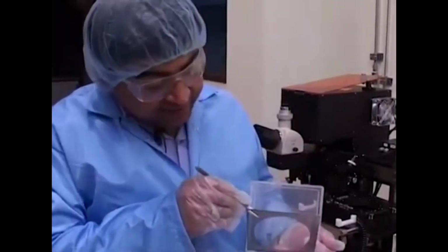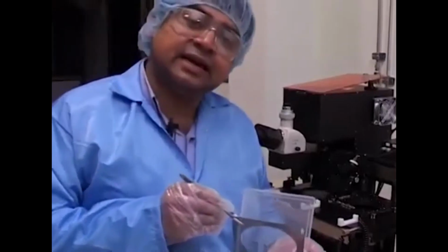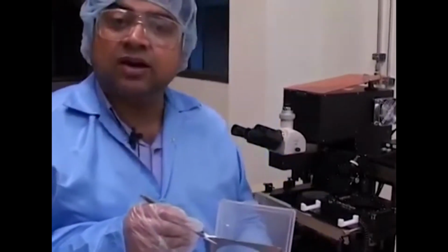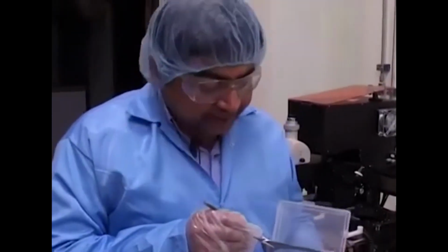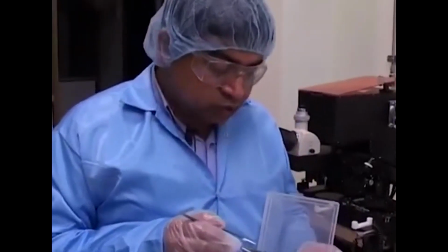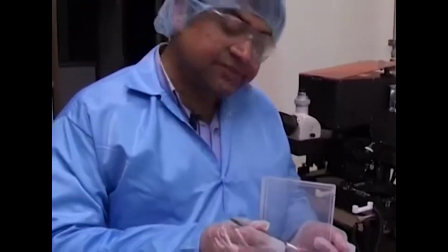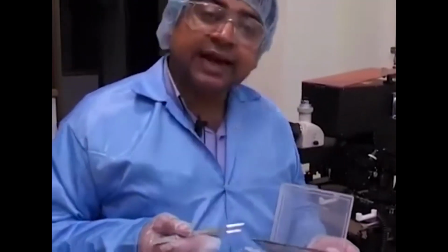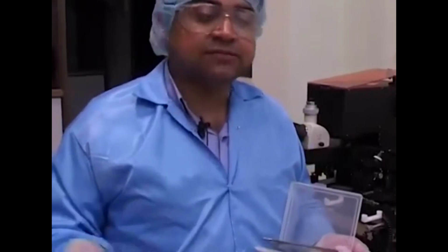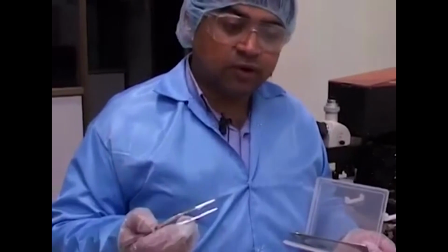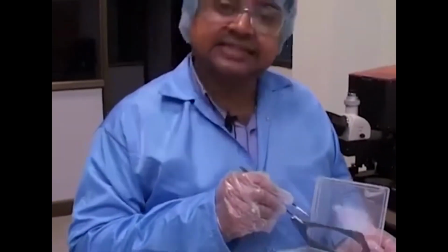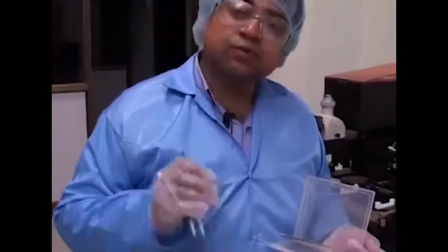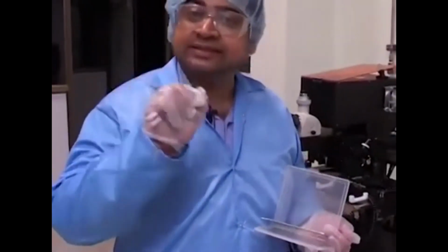The mask is made in a glass plate which is close to 900 microns thick, and so it is a very good idea to have the metallized surface in proximity to the coated wafer. 0.9 mm or 900 microns is enough for a beam of light to get hugely diffracted, so if we were to do it the other way around, with the glass side sitting on top of the wafer, the features would be much larger in size because of diffraction effects.